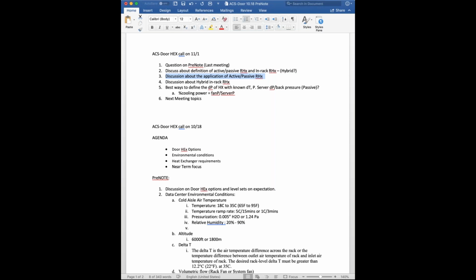Yeah, I mean, a kind of ideal way. A couple of benefits of this concept are: one, no containment required, maybe. That could be a significant process and cost saving in the data center. Or we can also minimize any concerns about recirculation happening, because the way it works, the recirculation is actually better for capturing all the air. And second, maybe you can eliminate CRAC units, or another way to say that is we can have a better real estate benefit. Yeah, I agree with both of your comments.